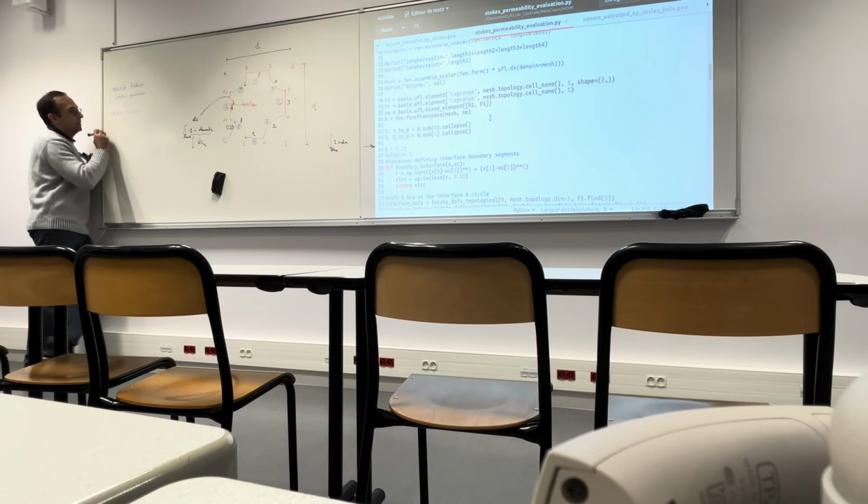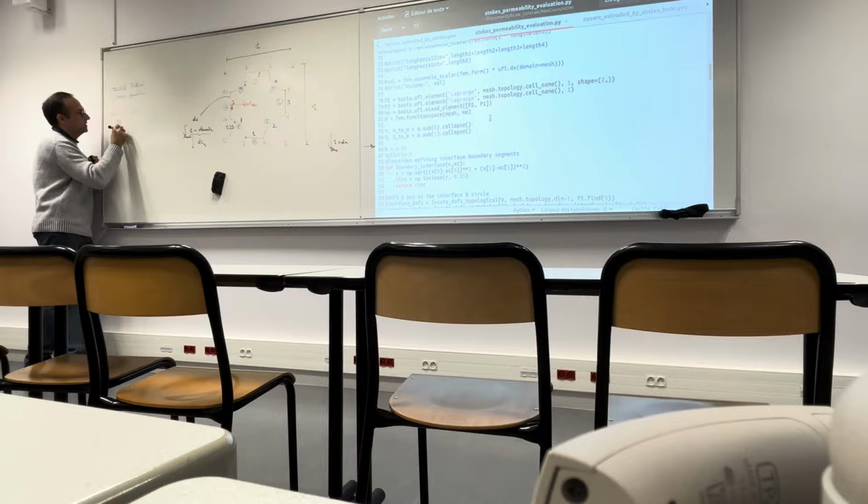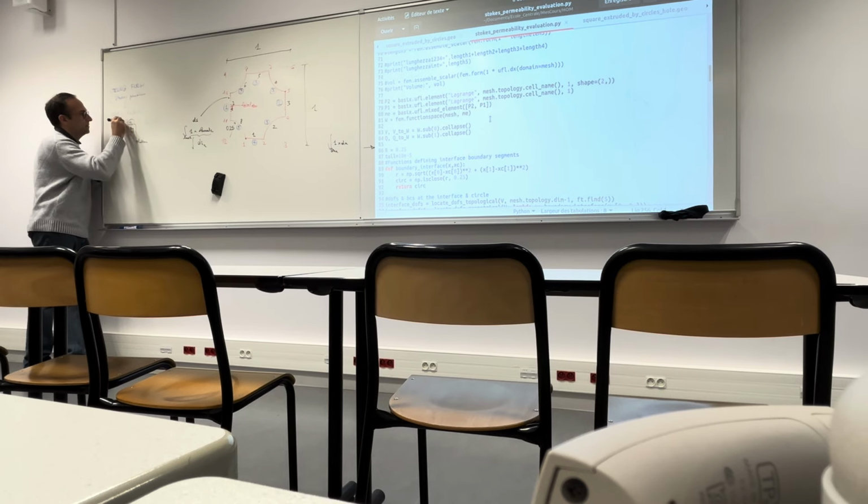And the weak form is written as the integral over the domain of, for instance, in our case, among the other terms, there will for sure be a term like dvi by dxj, dui by dxj, where the u, for instance, is the solution, and the v is what?